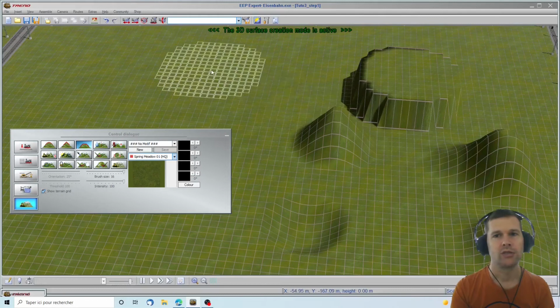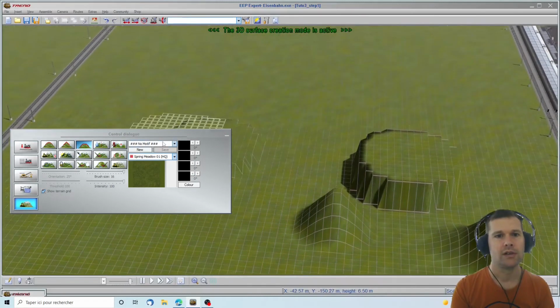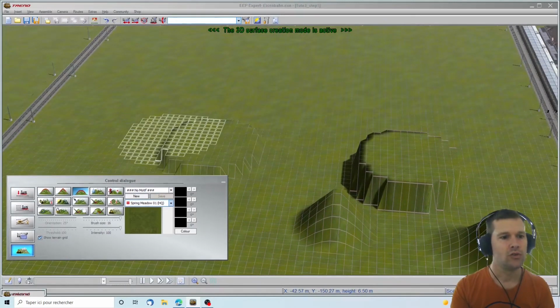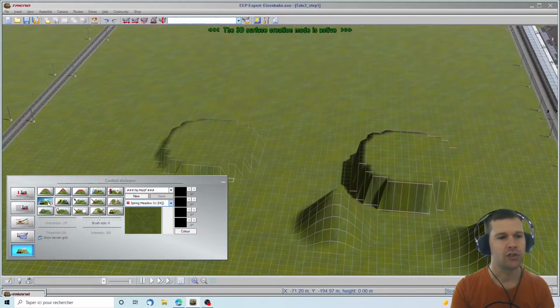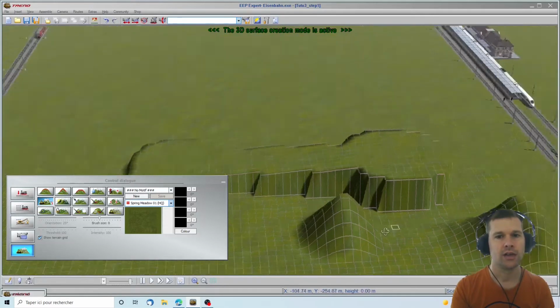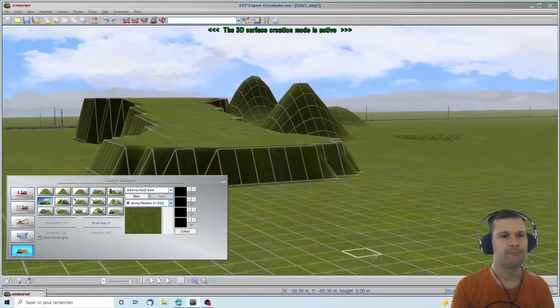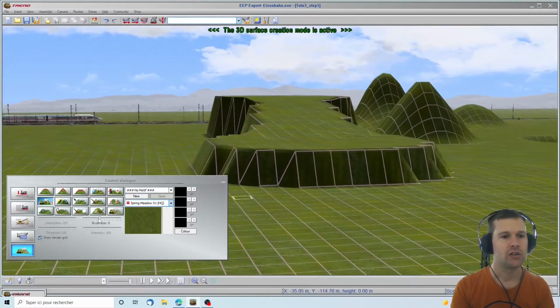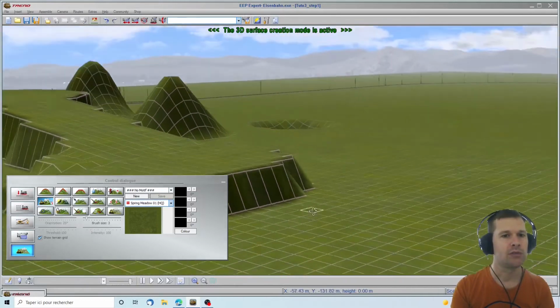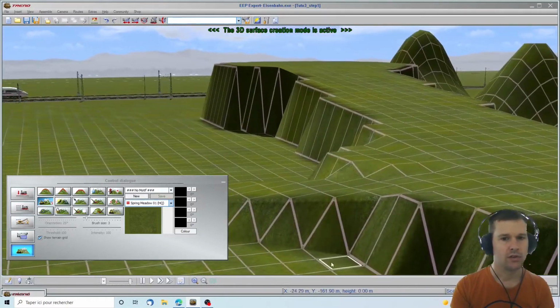Let's say I do the same here, and I want now to use that function here to make a slope from here to the other summit. There you have it. There you have your slope. You can change here the size of the slope. Let's say I want it to be 3. So I'm using this here, I'm going there. Here you have your slope with 3.